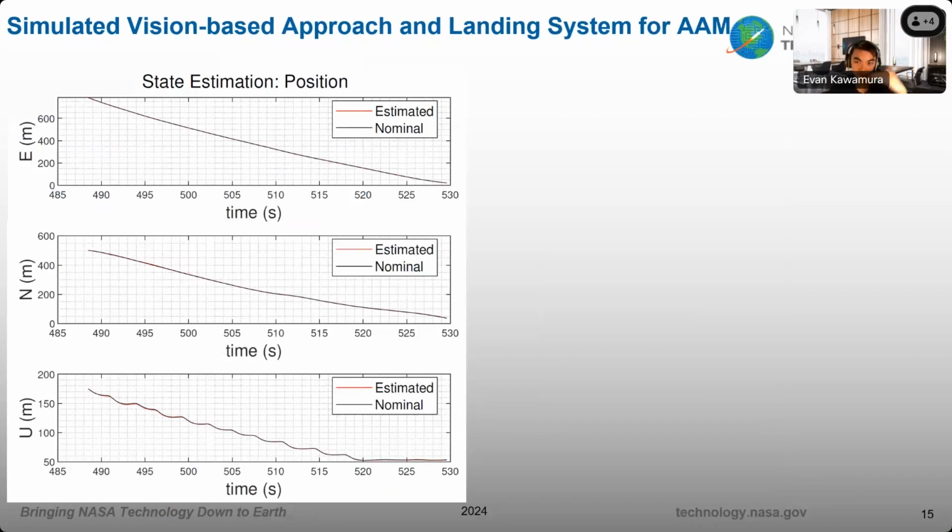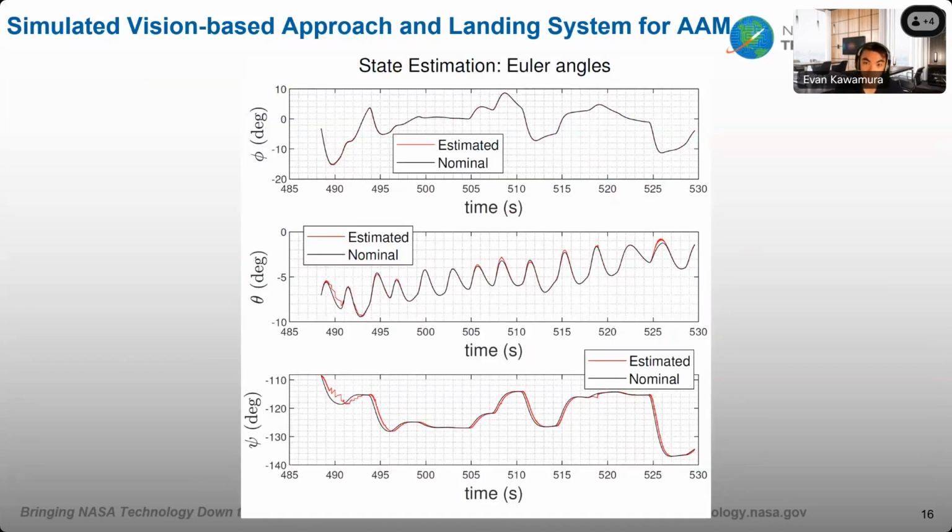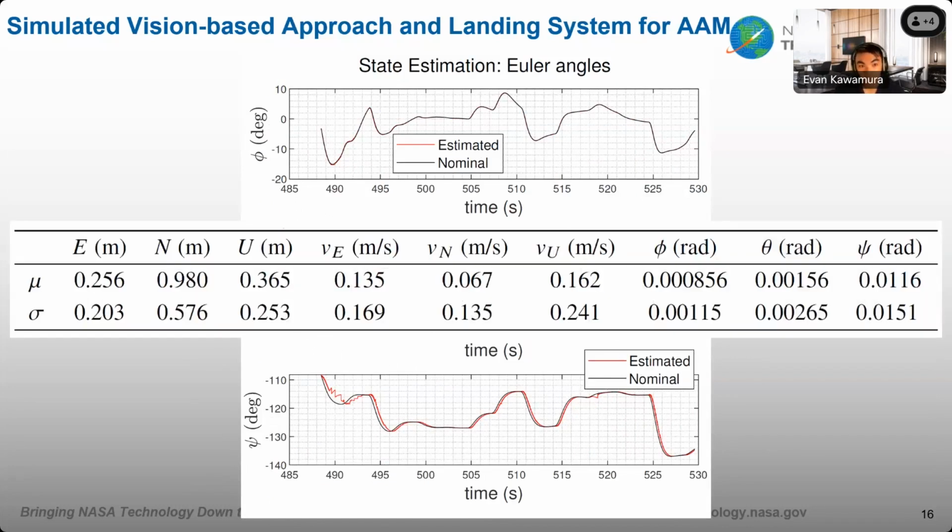There's that staircase-like descent. If you look at the U subplot at the bottom, this again is because the quad model has this waypoint-based controller. We also got some accurate velocity estimations with some minor errors. And if we look at orientation, it's pretty good, with some small offsets or fluctuations. Overall, we have sub-meter position accuracies, so we do beat GPS, assuming we can get consistent composite measurements.